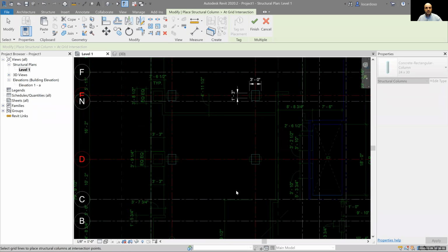If the column is not in its correct direction, this is where Spacebar is your friend. Remember, we're still in preview mode. You see that we have two options on the ribbon, to finish and to cancel. So that means that we can now begin to press Spacebar, and you can see it's rotating. So after it rotates to the correct direction, go ahead and press Finish.